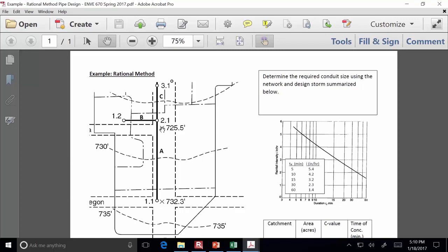if you make the pipe really steep for a long time, then that means it's going to be getting deeper and deeper below the surface. And so over the long run, the pipe slope and the ground slope have to either match, or you have to lift the water back up again with intermediate pumps occasionally. All right, so